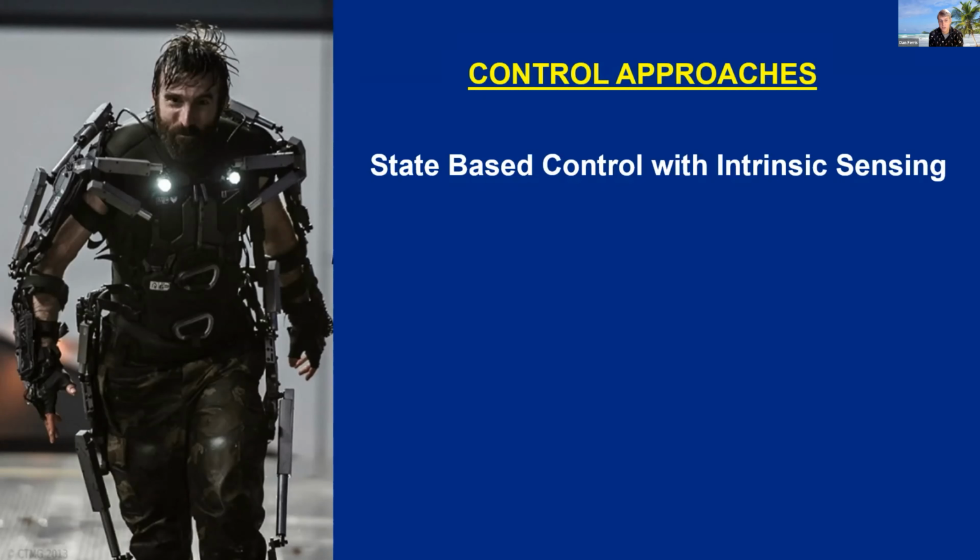This approach actually works fairly well when you have a rhythmic, cyclical task where the last few movements are very similar to the next motion, because you can see what the intent of the human is in terms of the motion, and then you can try to reproduce it. So if you're walking at steady state speed on a flat level surface, the success is quite high. It becomes a little bit more difficult when you're doing acyclical activities, some discrete motions of the upper limb, or you're trying to react to the environment. Imagine moving through a crowded subway where you're stepping around people and each step is really different from the next step.